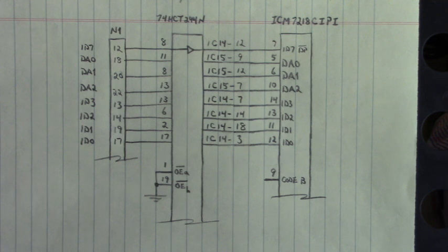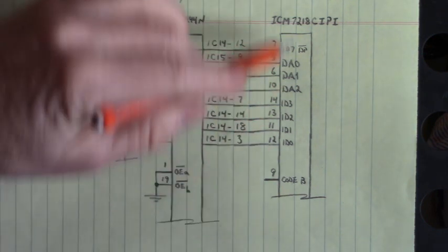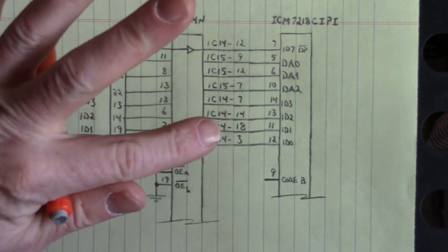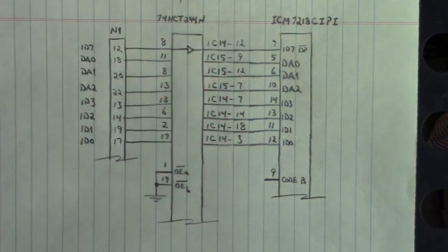Here is one of my drawings of the circuit of the Schlatter SWEP05 operator panel. Now, to turn on the 7-segment displays, this IC right here is used. There's 5 in that panel. Their part number is ICM7218C IPI. That C is very important.